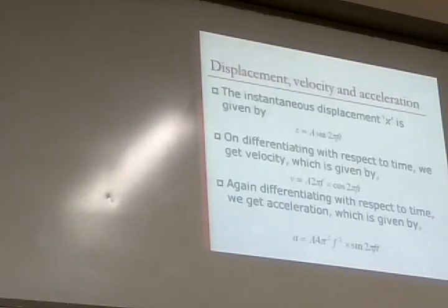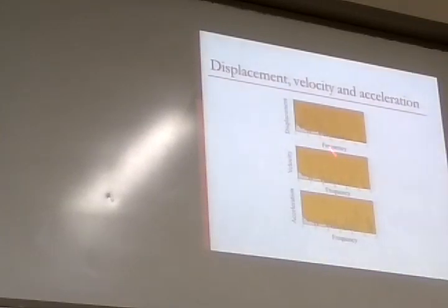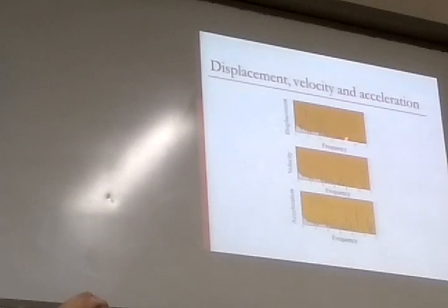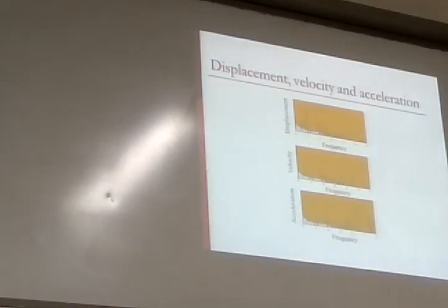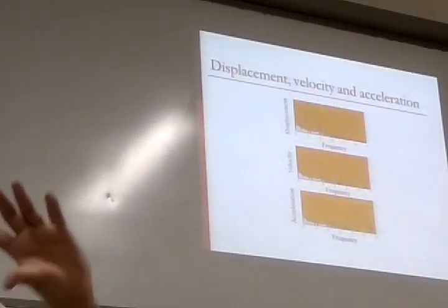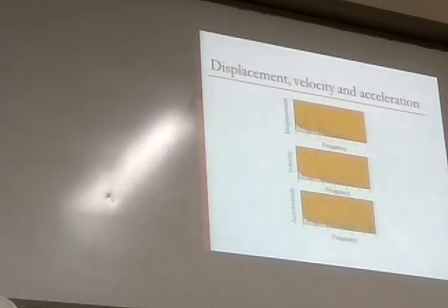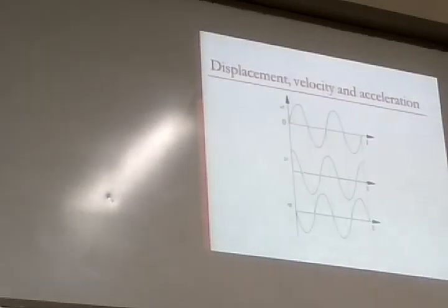I'll show you some typical examples. Real machinery signals will look like this. This is the displacement signal. So if these peaks are small, all the peaks are small, that's a small vibration. If all the peaks are high, your average will be high, so you will have a higher vibration. So average is a measure of the vibrations.